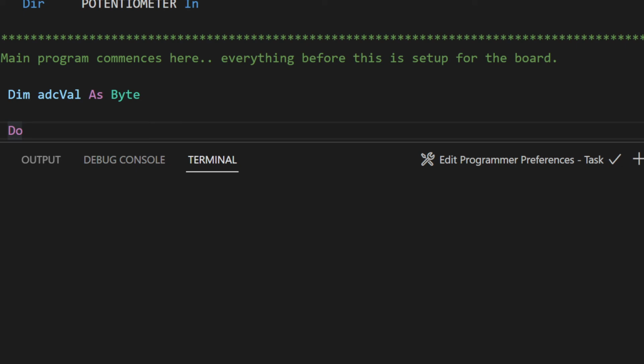These are all the programmers you could select. I don't want you to change those yet. We'll come back to those later in the week. Compiler: I want you to change it from verbose mode to suppress the summary mode. Verbose is what it is now, and there are 3 different levels. You can have verbose, you can turn that off, or suppress. I just want suppress because it's going to give us a nice little short report.